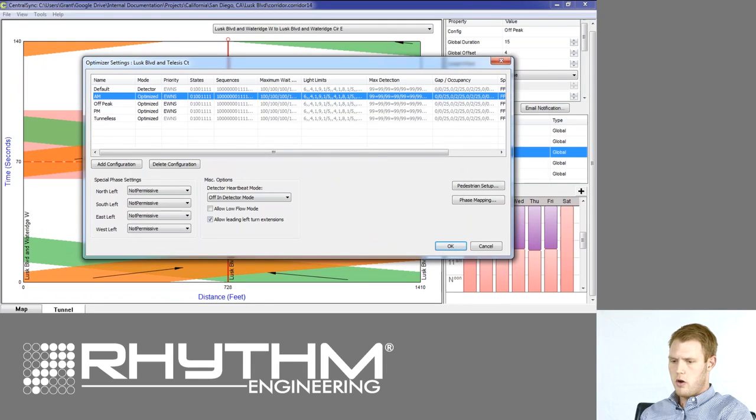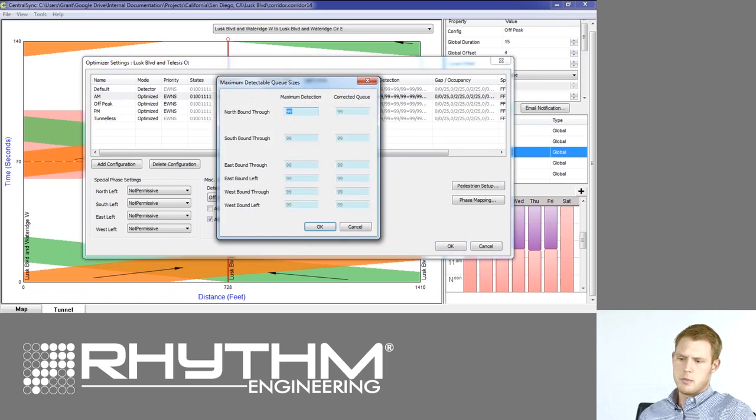The next column over is the maximum detectable queue sizes menu. In here, you can manually adjust the queues that InSync sees. So a couple different use cases for that, the first one being to inflate the queue that InSync sees. So maybe, for example, you have a camera view where the approach curves off and the camera can't see the full queue. You can go in here proactively and inflate the queue. For example, if InSync sees 5 or more vehicles, schedule like there's 20 vehicles present.